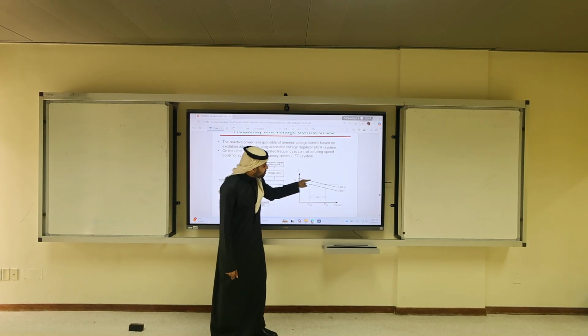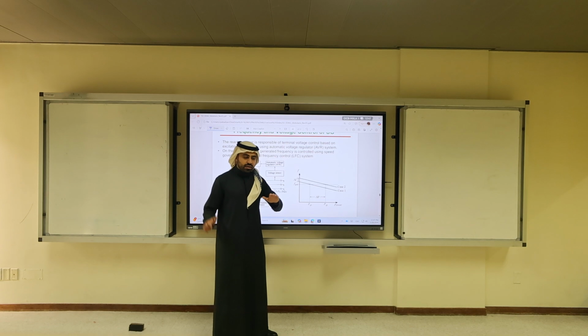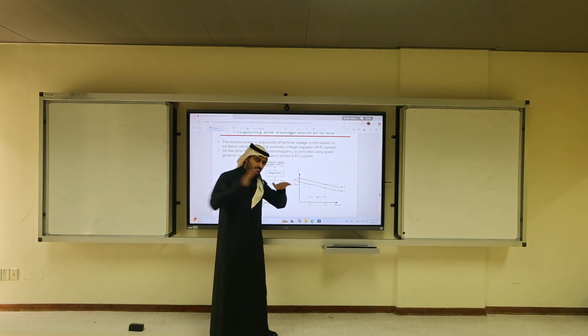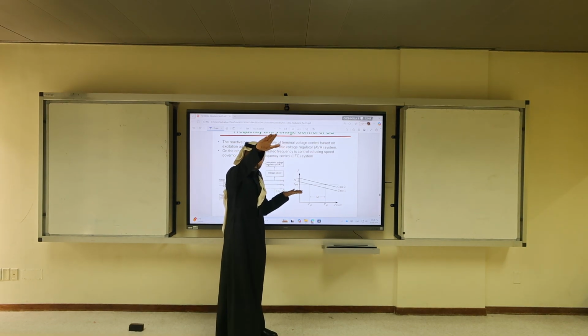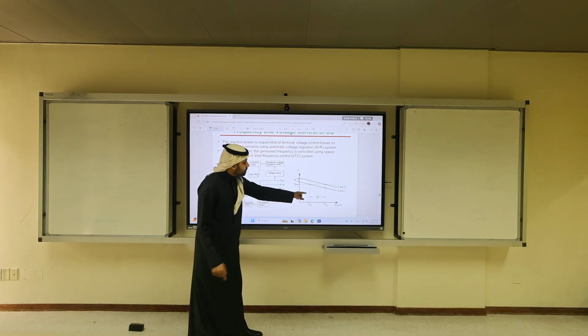And it's measured in these curves. So we're going to have a delta F, minor delta F. If you push more fuel, there is a minor delta F. The whole grid frequency is 60, but the frequency at the terminals of the generator may not be 60 because I'm increasing the real power.